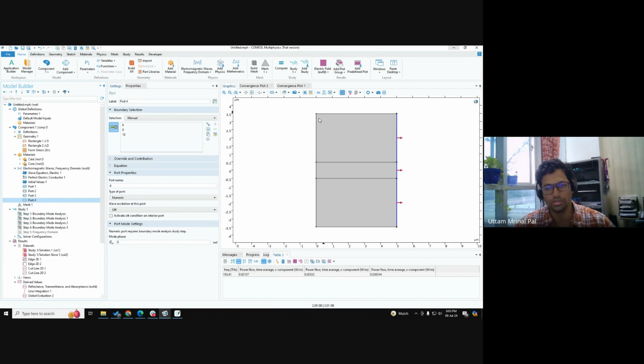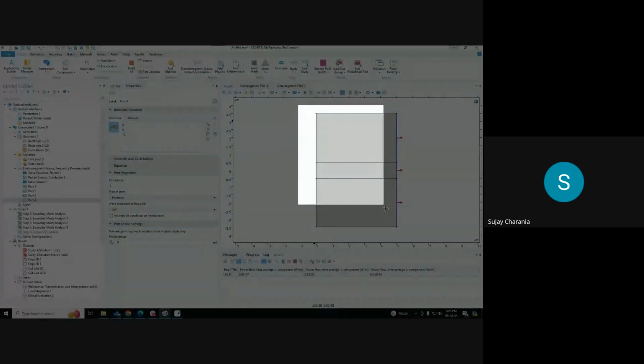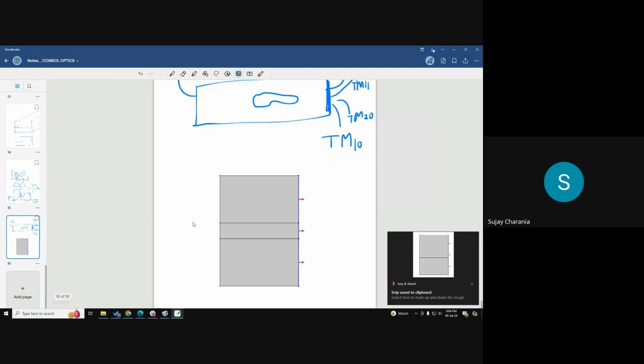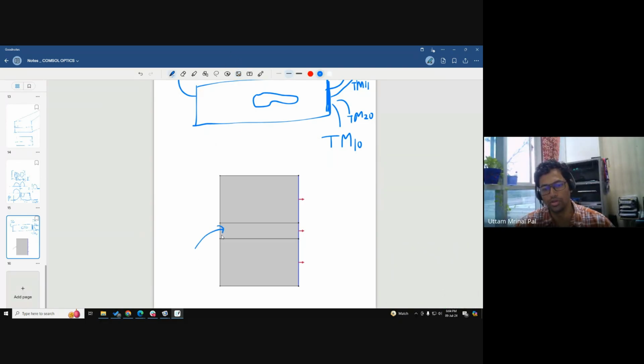So here, what I'm saying is that you are catching all the power that comes to the output, and then you are reading through the different ports only the particular mode power. Correct. So here I'm launching using port 1. That is the whole thing. Over here I can apply as many ports as I want: P2, P3, P4. Assuming there is some kind of conversion happening over here, we launch the fundamental mode, but for example P2 is for the fundamental mode, P3 could be for a higher order mode, P4 could be for an even higher order mode. So all of them I can capture using this.